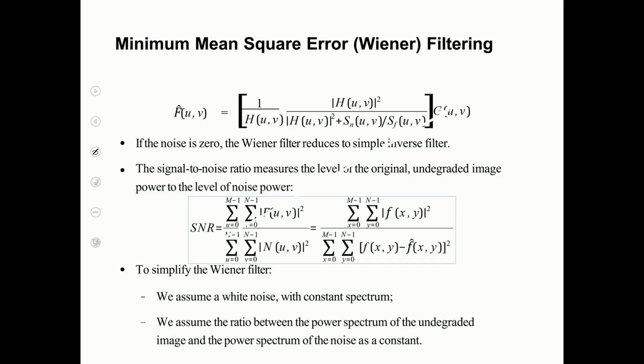It's like a signal power to a noise power, which is SNR. Okay, so how to calculate the signal power? Just square all the terms, sum them, get the signal power, right? And similarly in the frequency domain, using again the Parseval theorem, get this, right? And similarly, signal power, then the noise, how can I find the noise power? By subtracting the original signal from the estimated one, and this becomes the noise power. And similarly here as well, subtracting them, get this.